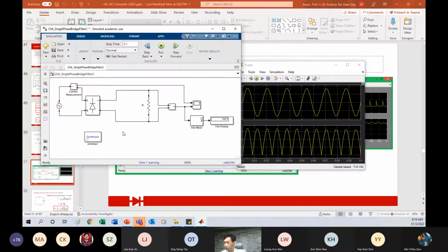Of course, like I said, even small ones, like your charger, which is basically an AC-DC flyback, don't really cause a lot of problems. That is subjected to, like, every house maybe having 4 or 5. That is still okay, because if you have about 5 chargers of 30 watts, or even 100 watts, the most is only 500 watts.